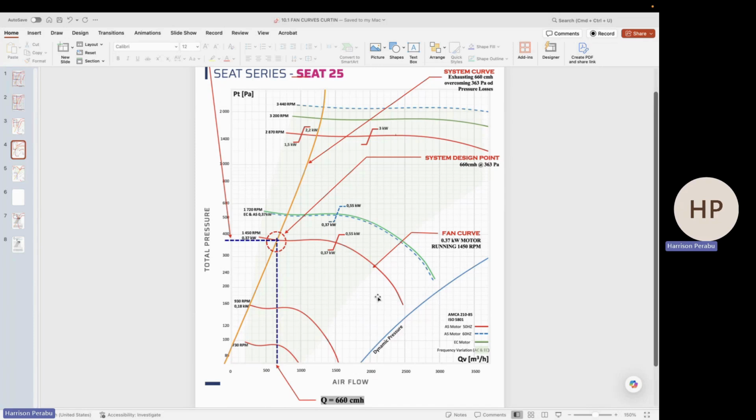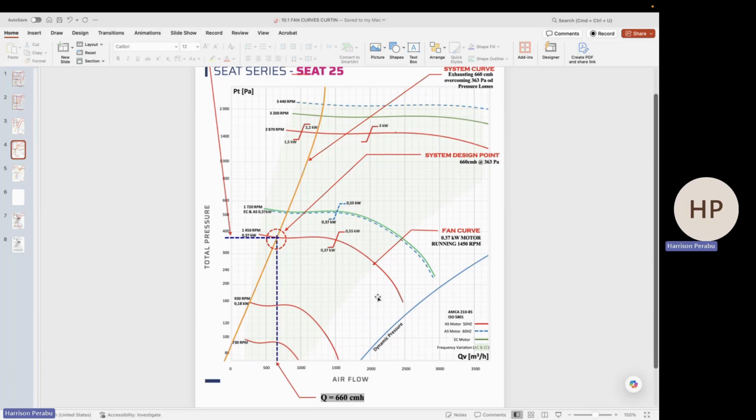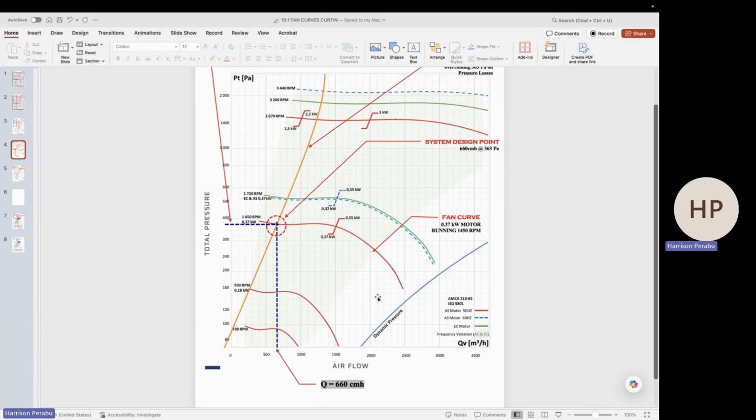But regardless of that, the hood plays an important role in providing a good capture efficiency, ensuring that it requires a small amount of air with highest efficiency. What does this mean? This means that if I use a canopy that is huge, a very large opening, and the distance most of the time is away from the emission. For instance, let's assume you have a furnace at a table height of about 1.5 meters, and your canopy is placed at about 2.5 meters. So you have about 1 meter capture distance.